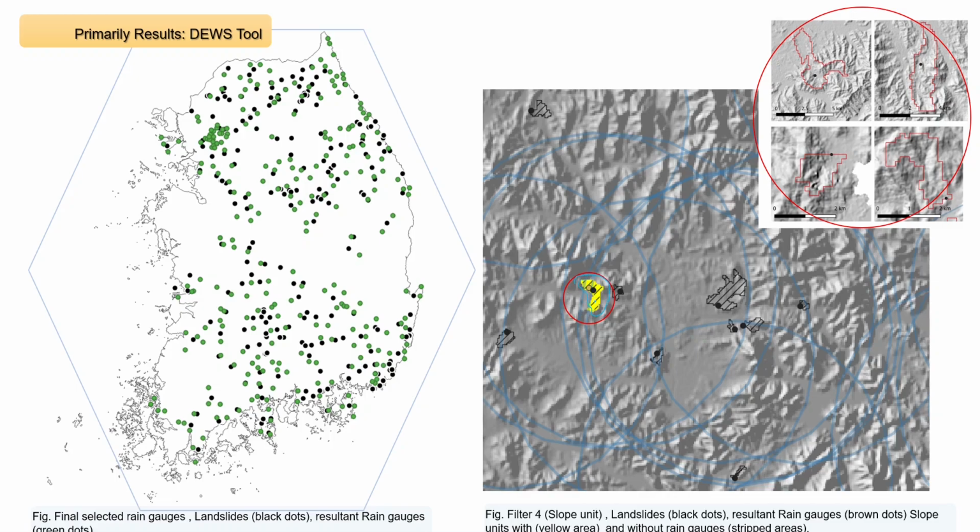If you see, you will notice that the shape is not smooth. Why? Because we are dealing now with the 100 meter raster. Actually here we applied 100, as you remember before in the settings. So 100 means every pixel here is 100 meter. So definitely the slope unit is very small, because if you look at the mountain here, 100 meter is quite big, so it will show you something like this. But later I added the smoothing, so this line will be smoother to understand the slopes.